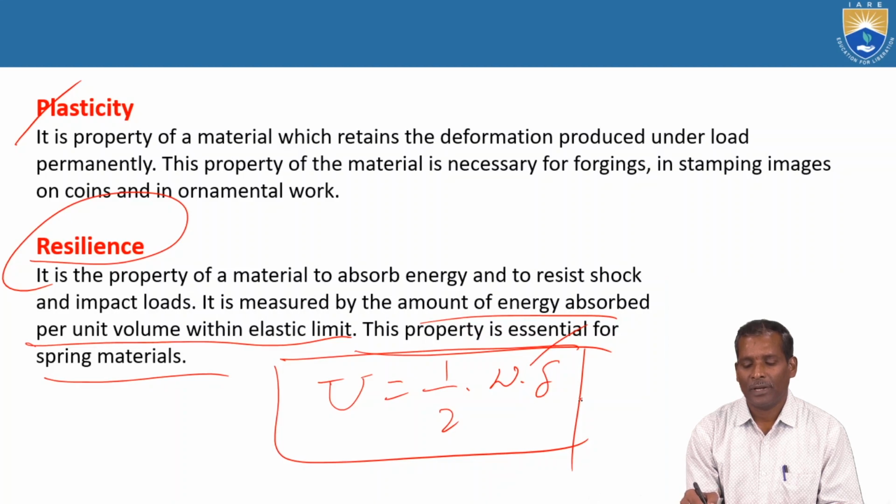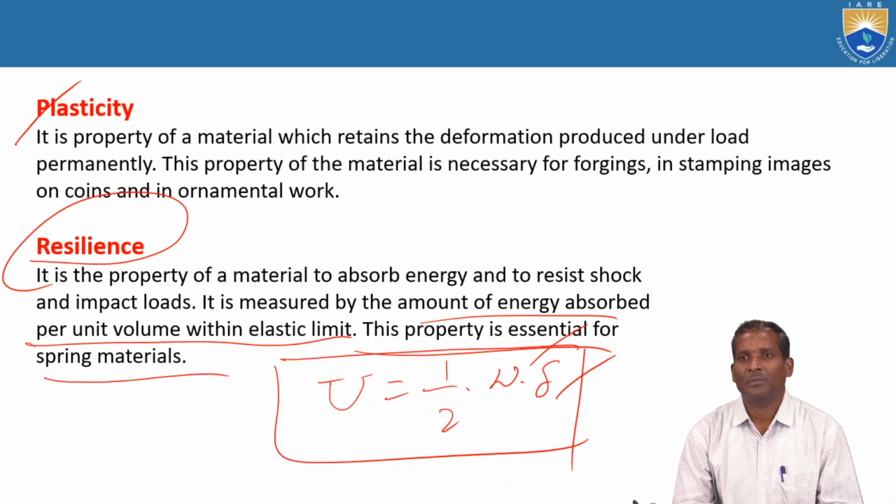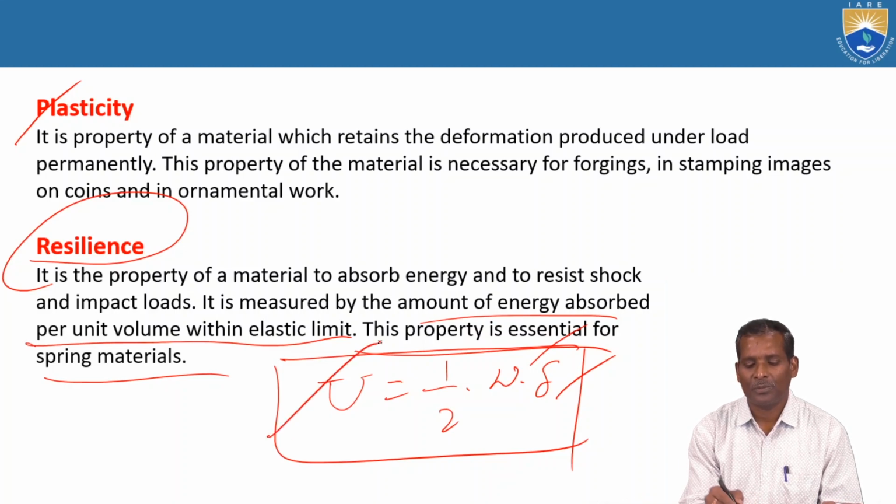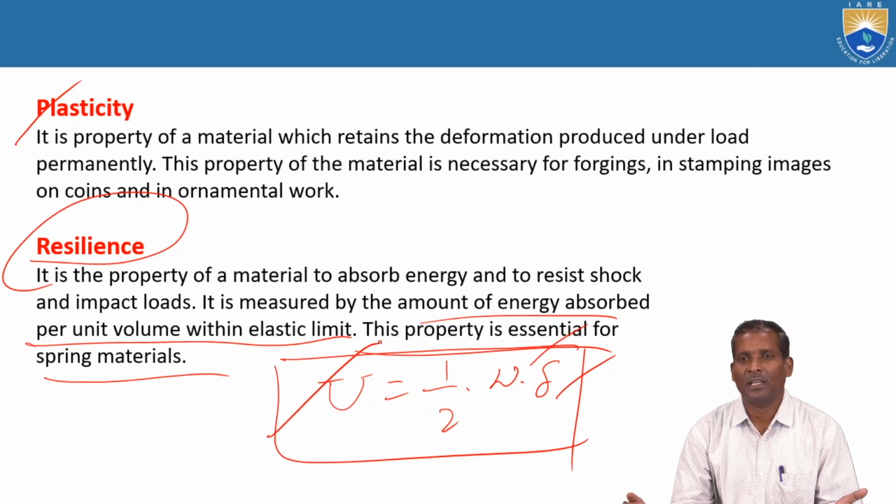Here W is the applied load and delta is the deflection. How much it is deformed, how much energy is absorbed, the total energy absorbed you may calculate using this relation. In spring materials, this property is very, very important.